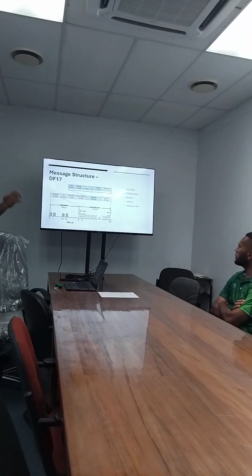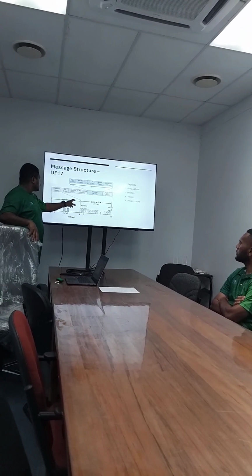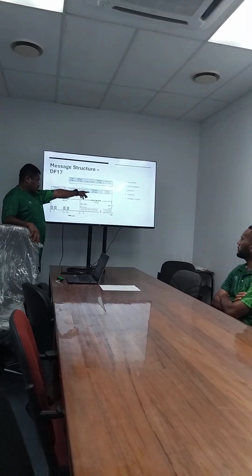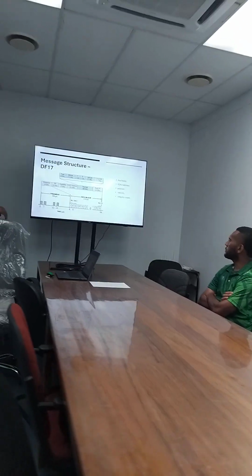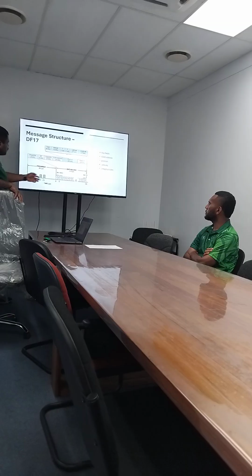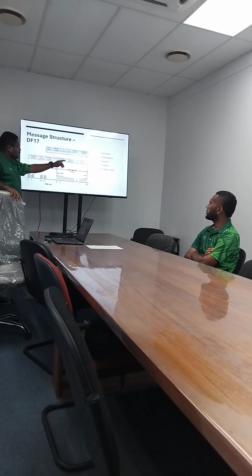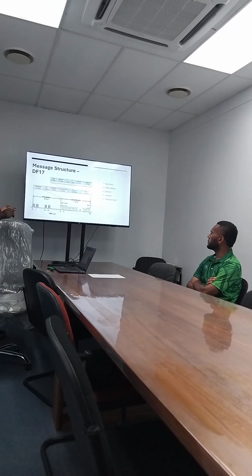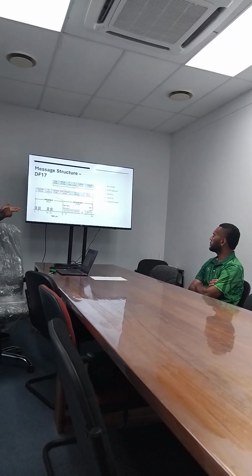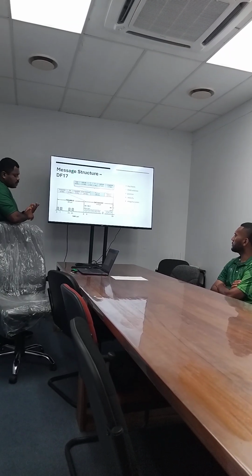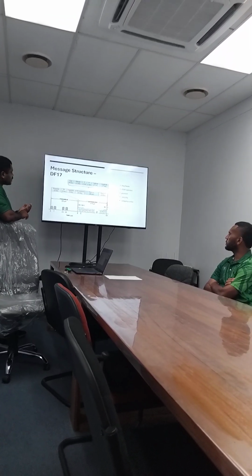We basically look at the data block from the 9th bit to the 32nd bit. The main key fields, see on the right, is the ICAO address, which is 24 bits. The ICAO address will be either the registration of the aircraft or the aircraft type.